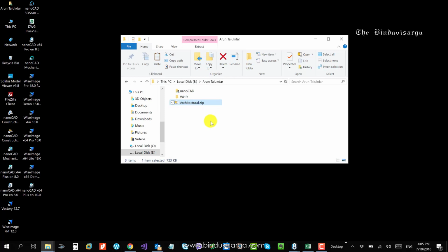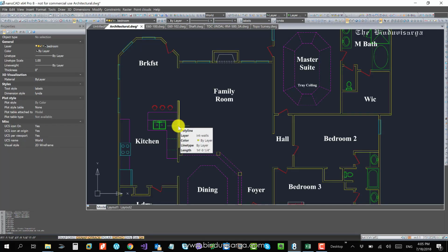This basically means that you are sending all the resources that you had used in one specific DWG file. So in that way, that particular client will never produce proxies or miss any objects on their local system if they open that particular DWG file from the directory you had sent.